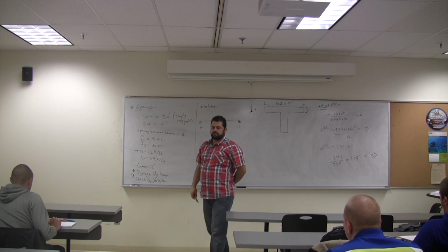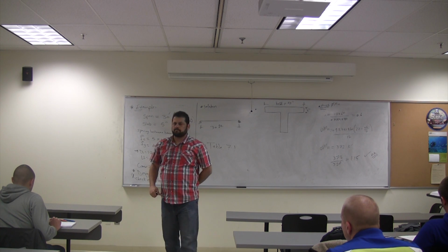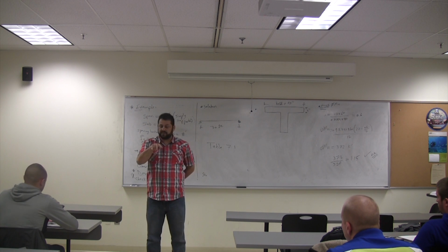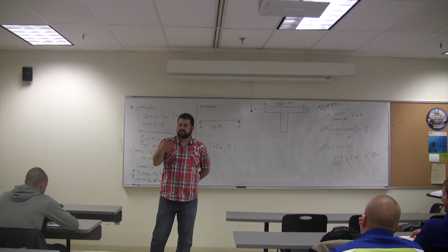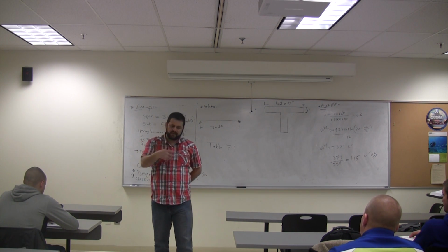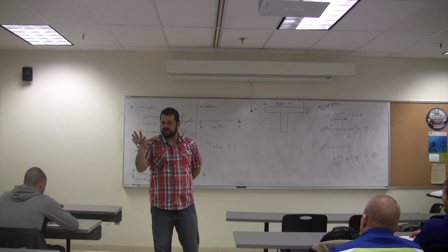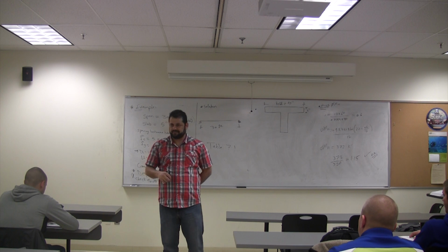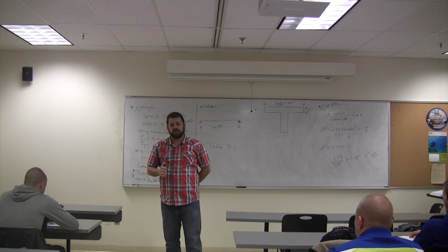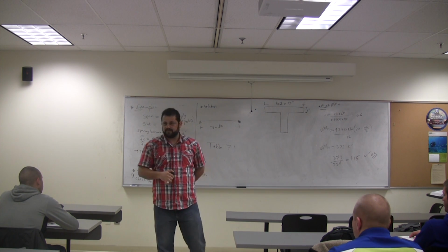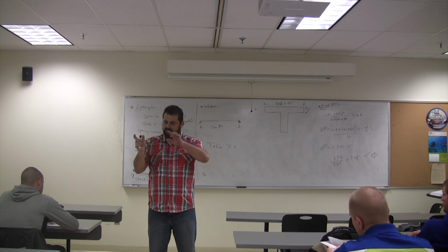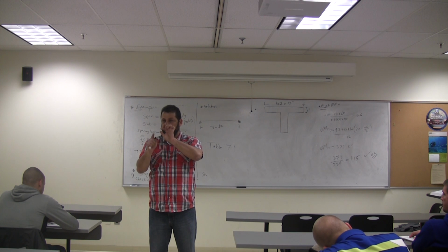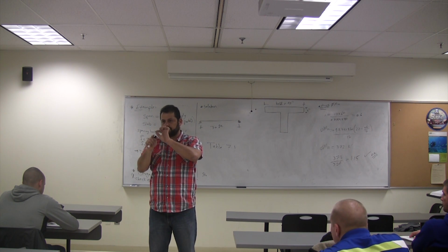It's going to be less than the 2 inches cover. The clear spacing between the bars is determined by the maximum aggregate size, or as a common practice, not less than db, the diameter of the bar. Diameter of the bar, or d_b, is the cover? No, they took the diameter of the bar, because the cover is different. The cover to the center was 2 inch, right? You take half of the number 10 from there, you take a stirrup around it also.